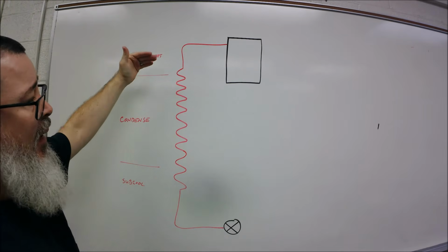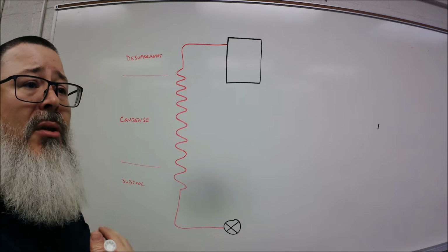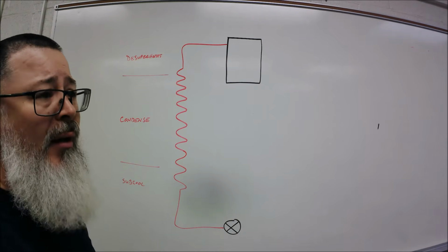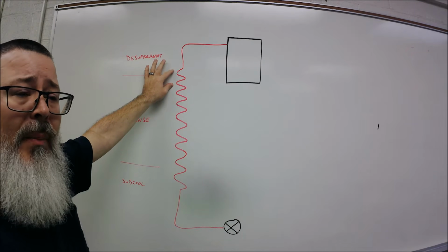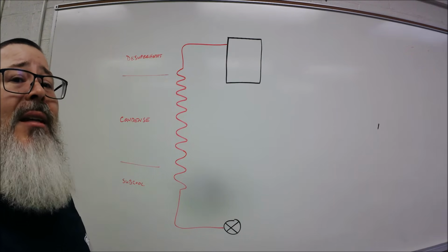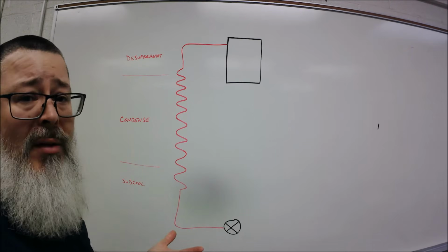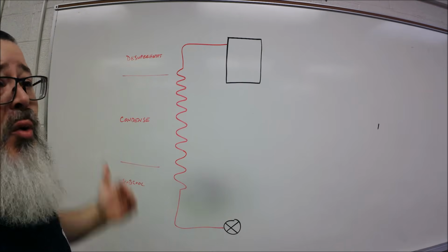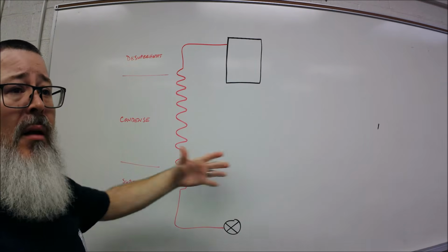It's going to get into the coil, get into the airflow, and it's going to start to lose heat. And it's going to do it fairly quickly, but we'll use the first little portion of the coil to get rid of that superheat, right? We undo the superheat over here, right? The evaporator absorbs the heat, the condenser rejects it.